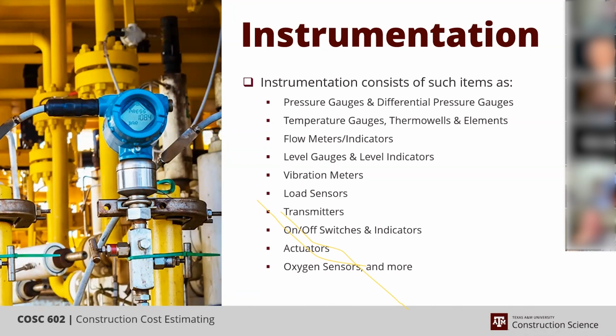A good example is that in older cars, there's a temperature gauge in your car dash, but that temperature gauge is reading the temperature of the water inside the engine. And there's literally a wire that runs from the back of that gauge through the dash, through the firewall of the car, and used to drop in and tie to an element that was screwed into the manifold of the engine, and that wire was transferring the heat.